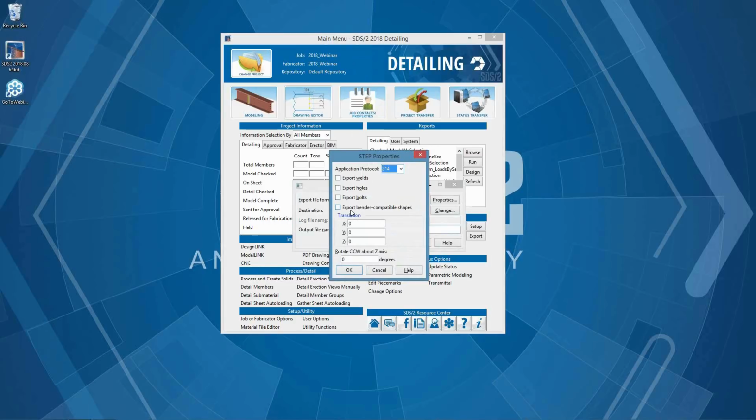When bender compatible shapes is checked, the system will try to export extruded profiles for pipes and tubes. You will want to check this option on if you are exporting to Bendtech, Sigmatech, or Advanced Fabricating. The other options are translation and rotate.